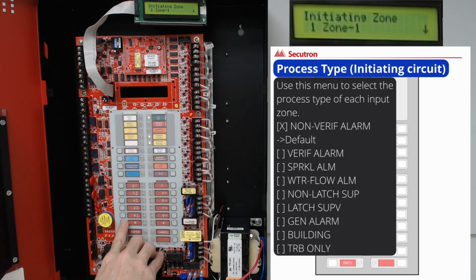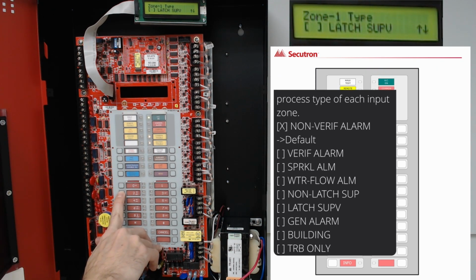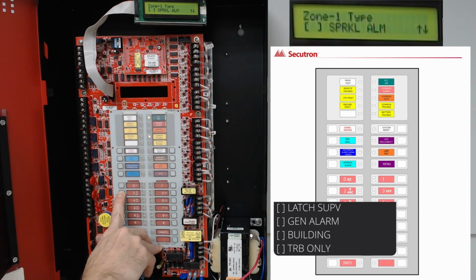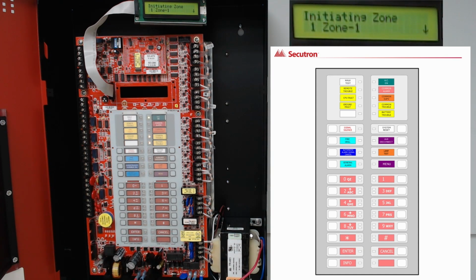When we want to program a zone, we'll hit enter to enter in that zone. The default selection for a zone is a non-verified alarm. The other options we have are verified alarm, sprinkler alarm, water flow alarm, non-latch supervisory, latch supervisory, general alarm, building, and trouble only. When you see the desired selection, you can hit the left or right cursor arrows to apply the X, and enter, and then cancel to go back out to the previous menu options. These same options can be applied through all zones 1 through 12. By hitting cancel, I go back out to the panel config options.